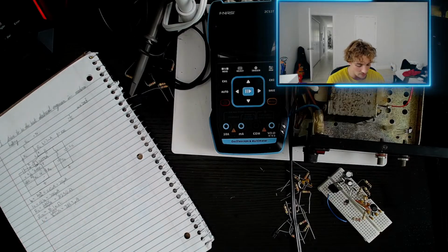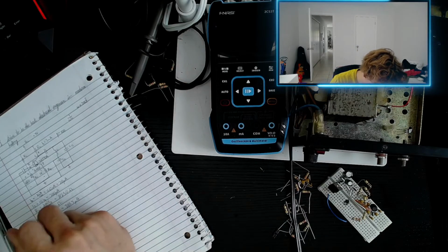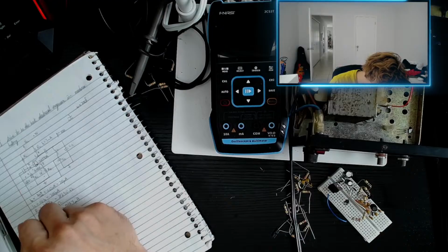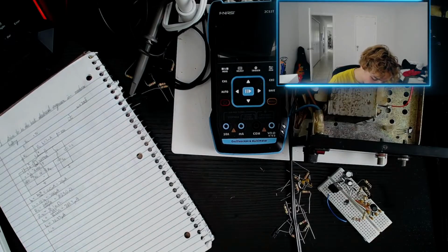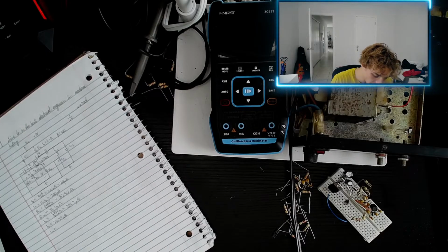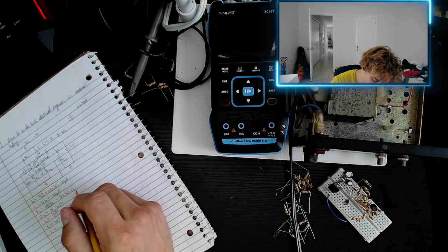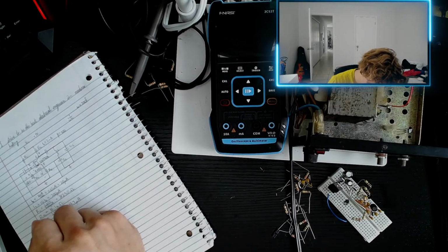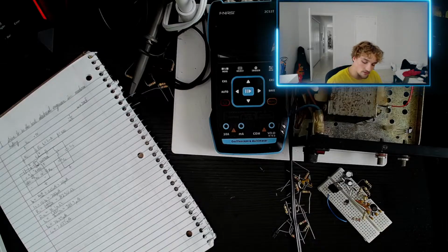That's going to be I2, so let's divide that by 10. Then we can assume our base current is IB equals 20.37 microamps. And we can assume our collector current is now 20.37 microamps times 100, right? Because we have this DC current gain, our beta, of 100, it's going to be 2.037 milliamps. So it's a little bit larger. That's fine. That's good.